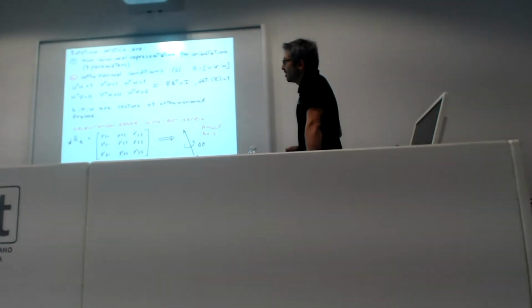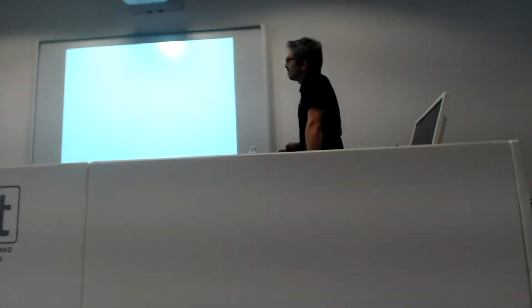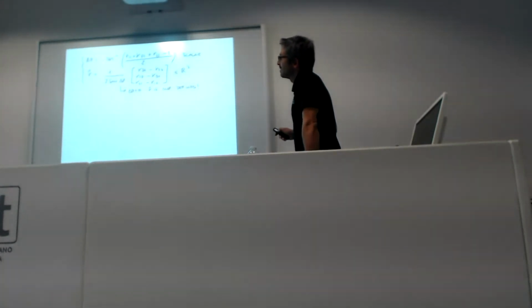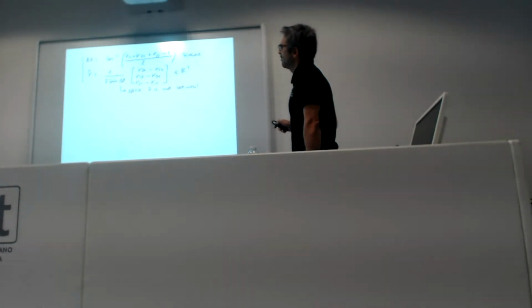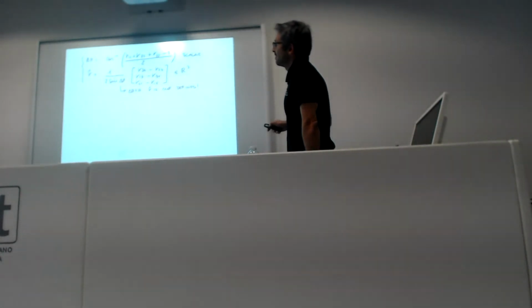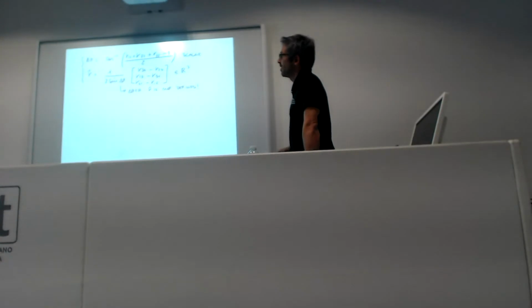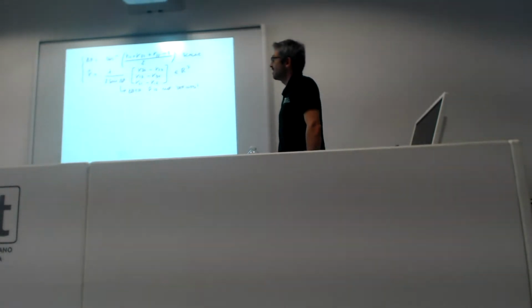So when we map the matrix into angle axis, how do we do it? You have this equation that allows us to relate the trace of the matrix to the scalar, and to get the axis this way. We need to take care, just to be sure that delta theta is not 0 in the code. Otherwise the axis is not defined and everything crashes horribly.